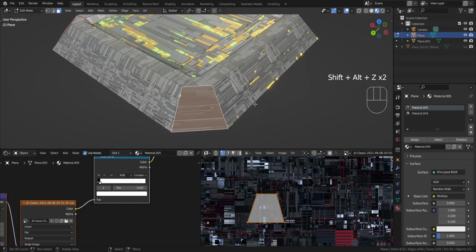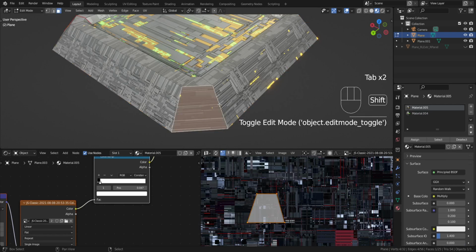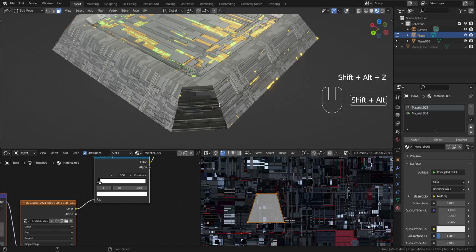So in Blender, to get rid of the overlays, so I'm in edit mode, it's showing me the selected face. To get rid of that, so I can see the effect much better without going to object mode, I can press Shift Alt Z to get rid of the overlay, but I'm still in edit mode, move things.